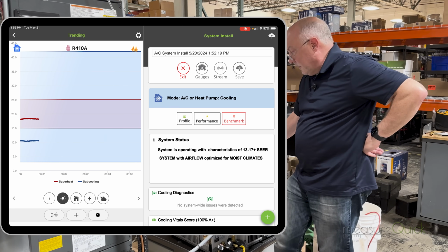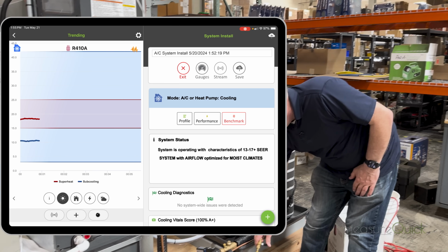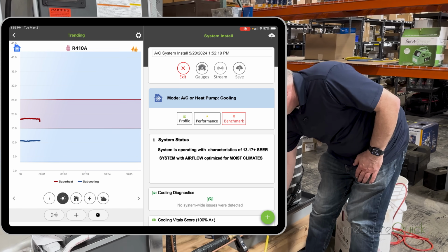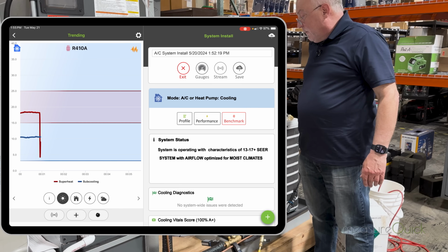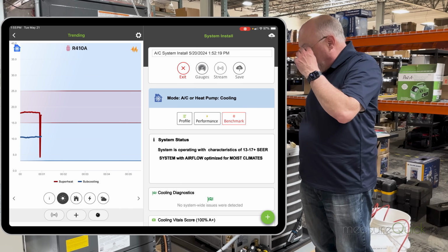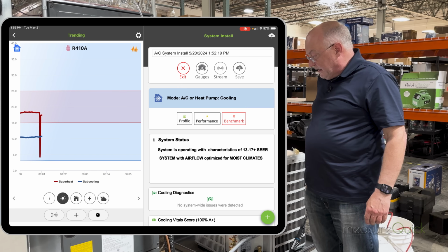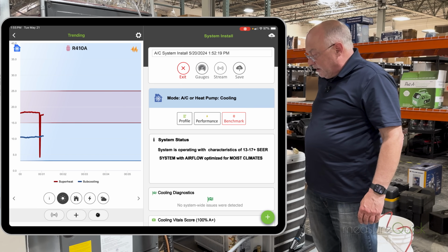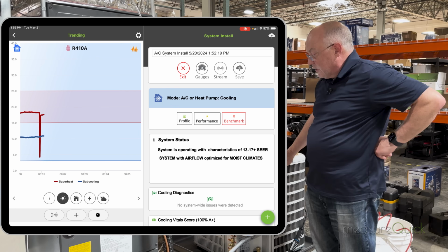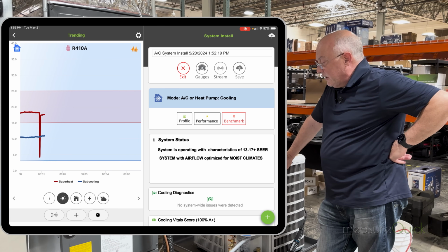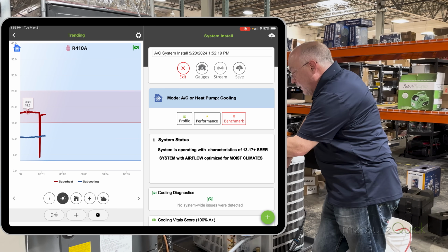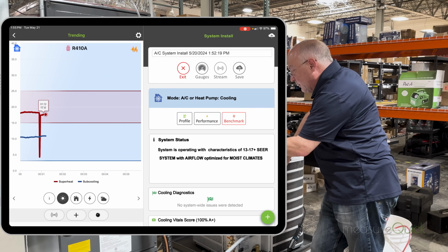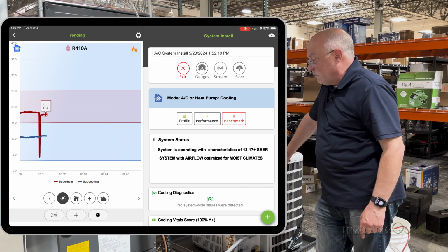All right, so we'll add another small amount of refrigerant here. When we added that refrigerant in, you're going to get a pretty massive change at first, but you can see now that it's dropped from where it was, and it'll continue to drop. We'll let it settle out for just a minute and see if it continues to drop off. So here we were at about 18.3 degrees of superheat, and now we're down to about 17.6.